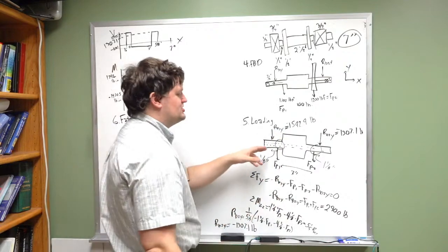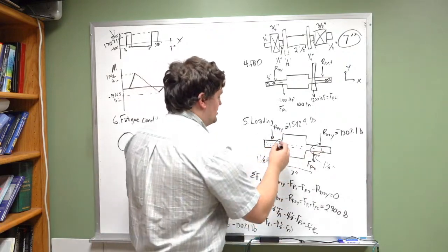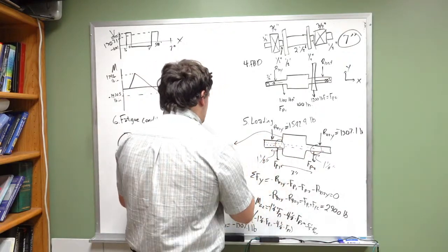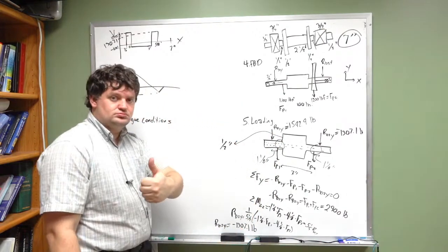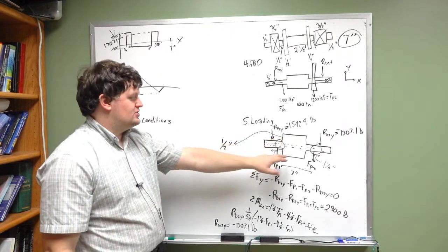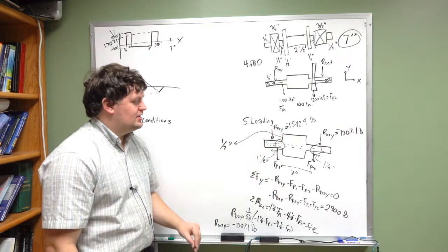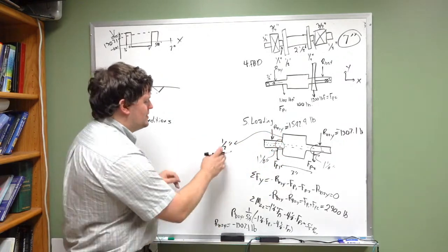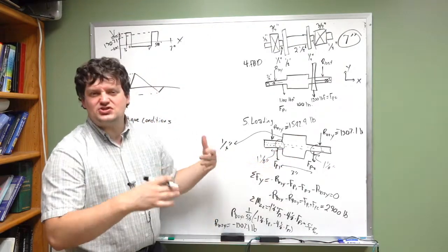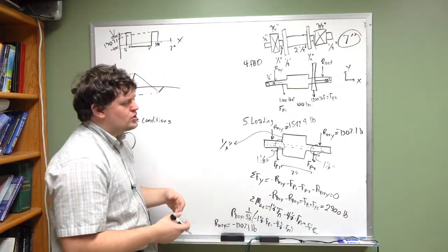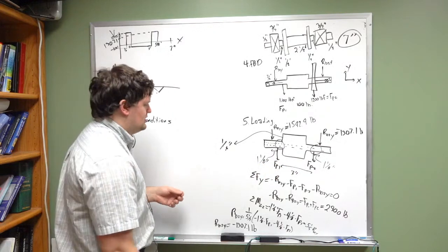Because the critical conditions occur right at the pulleys, it doesn't matter what our step is. It's going to be 1/2 inch. No, we'll make it a 1/4 inch. That way it's only a 1/2 inch larger at that size. It'll save us on machining when we go to machine this piece to have a smaller step.